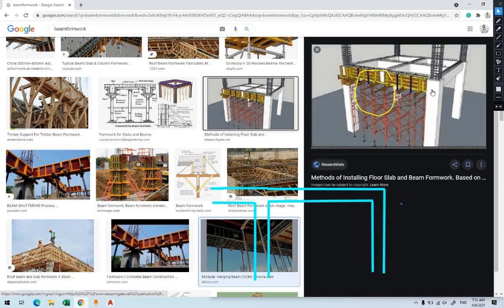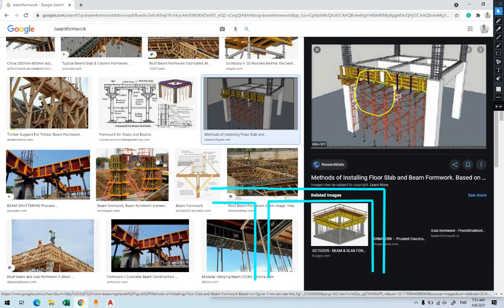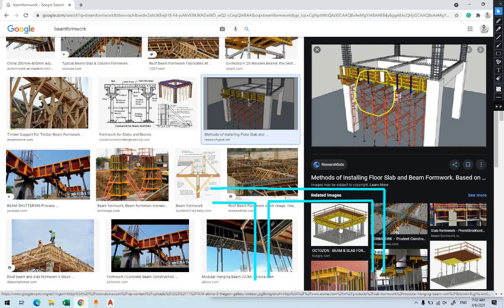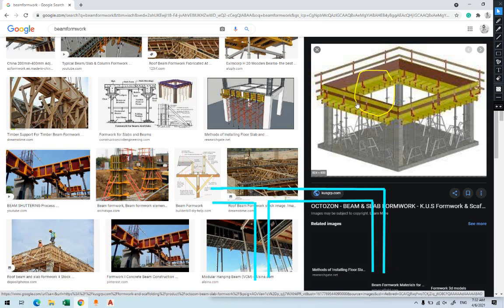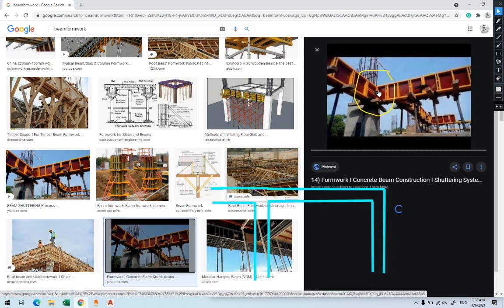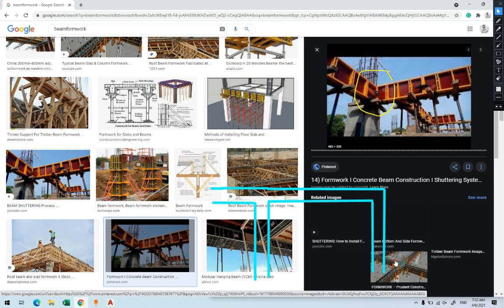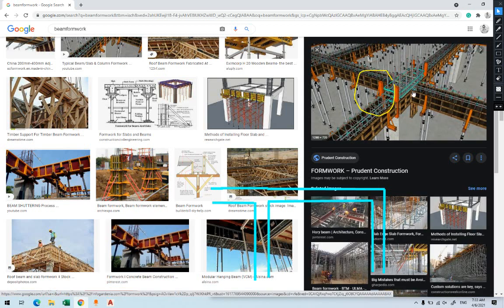Look, the side of the beam comes, this is, oh, this column here, this is wrong. Let's check something, yes, here. Realize that the outside should come over the column. It has to come, because this part of the column is not being cast, so it will be cast with the beam. So in this manner, you have to make sure you have a continuous line. You have a lot of pictures to look at. For example, look at them, they continue in this manner in order to understand what you're doing.